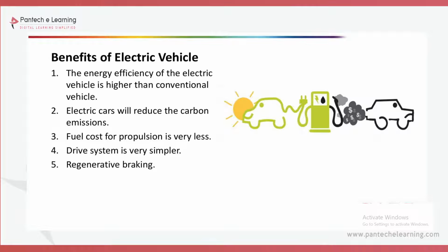With a motor, you go through a gearbox to the differential unit, and the differential unit to the tire, so the propulsion is very simple. If there is no gearbox, you can use a simple gear concept, forward and reverse. Some companies go from the differential unit to the tire, so the driving system is very simple. While using an EV, it will generate regenerative braking. Regenerative braking is nothing but generating power while the wheel rotates freely. At that time voltage is generated, and that voltage is stored in the battery.